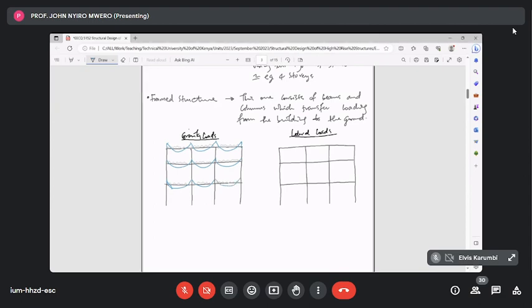These out of balance bending moments, like here at this corner, would be carried in the column in that manner, so we'd have bending moments in the columns. Again, this is from your analysis of structures.